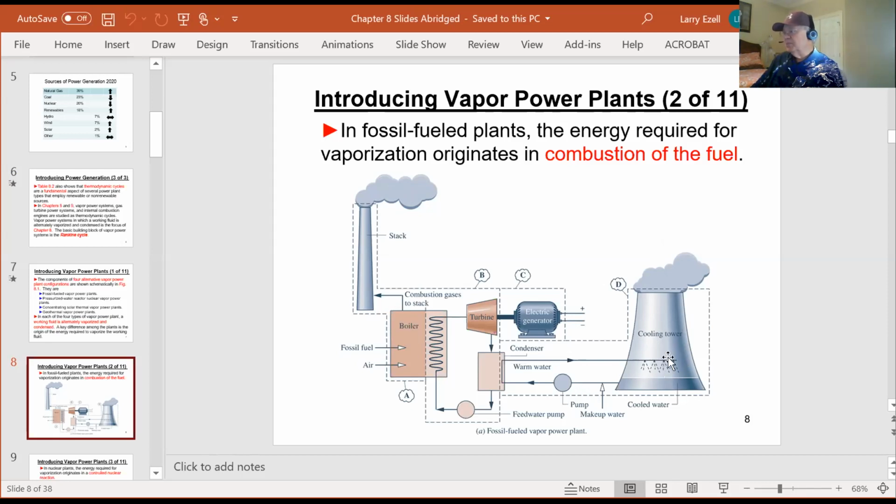The cooling tower is used to provide cooling water to help the condenser take this hot vapor coming out of the turbine and condense it back into water, where you can now go back through the boiler. And these two water flows here, the Rankine cycle and the cooling tower flow, never meet. They're in close thermal contact, but not in physical contact. This loop here you won't study much, but you would study that in thermo 2. Of course, you don't take thermo 2.